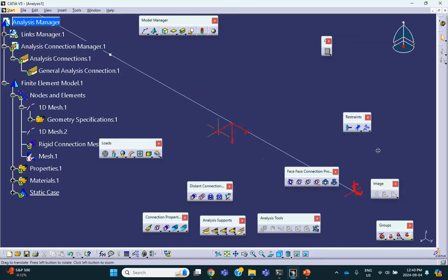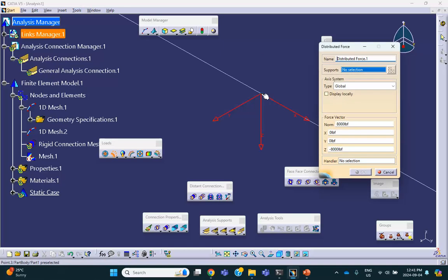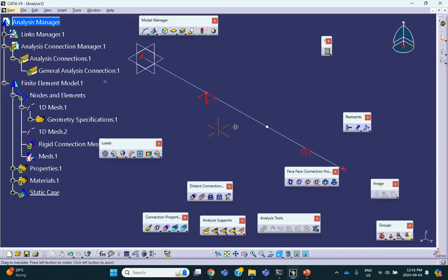And now, when I put a force of 8,000 pounds on that point, it will automatically be inherited by that node. So if you have not done this thing with the advanced meshing tool, you put a force on that point, the finite element module does not even see it. So where is that force? On that point, the value 8,000 pound downward. Okay, and then we say okay. We should be good, unless I forgot something. That should be good. So let's go ahead and run it.